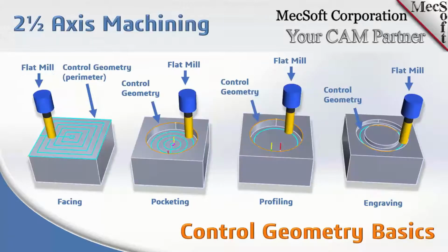Thanks, Don. Okay. Now here is just an isometric view of each of those examples. As Joe mentioned, if you start on the facing on the far left, you'll see that the control geometry extends out to the perimeter of the part to clear the entire face. And for facing, obviously, you can use flat end mills, facing mills, etc. Again, the pocketing, obviously, we talked about that. The flat mill is extending until it touches the control geometry at the perimeter of the pocket. And the same with the profiling.